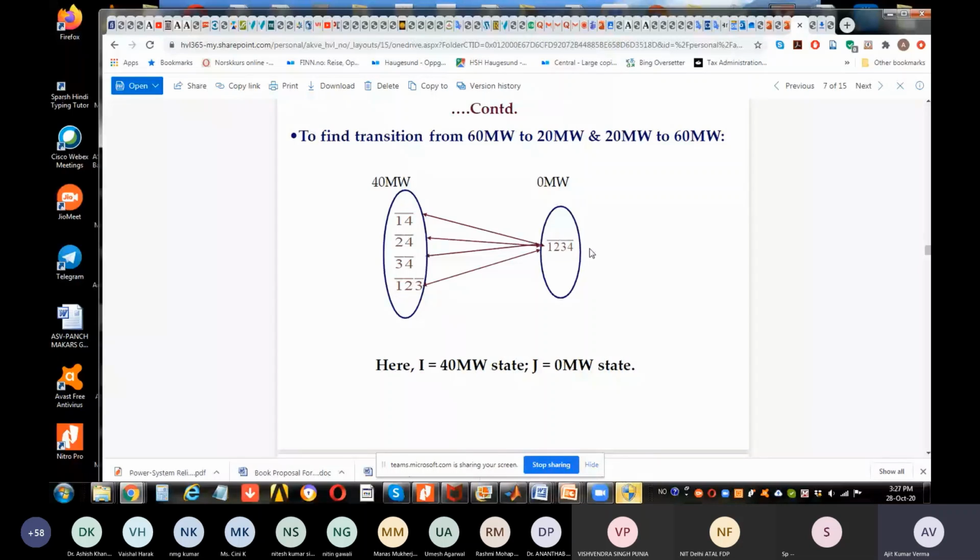And therefore, two units failing simultaneously, not that it is not possible, but the probabilities are going to be very, very low of the occurrence of that state. So the probability is so negligible that any multiplication with any terms would not make any difference. So that's the mathematical logic why we do not consider simultaneous failures of two or more units, more than one unit.